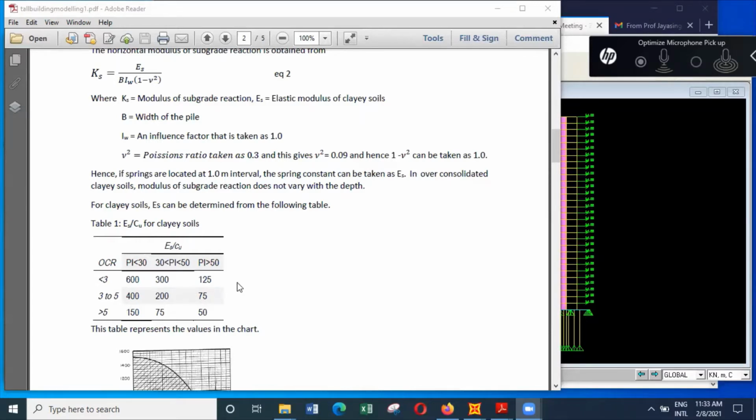So you can see when you have clay soils, it may be a good idea to find the liquid limit and plastic limit as well. You can request liquid limit testing to be done when you have clay soil samples, so that you will be able to make a reasonable estimate of the plasticity index. Based on that, you can decide the ratio that you are going to use.